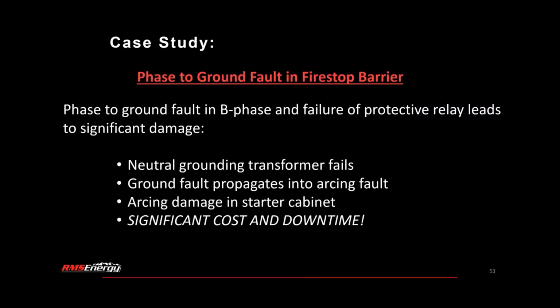So once the transformer was lost, the ground fault propagated into an arcing fault within the bus. The arcing caused significant damage inside the bus duct, but it also led to additional failures in the starter cabinet, ultimately resulting in significant cost to repair and downtime.